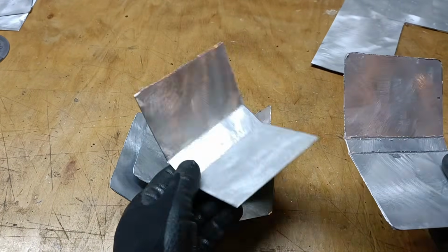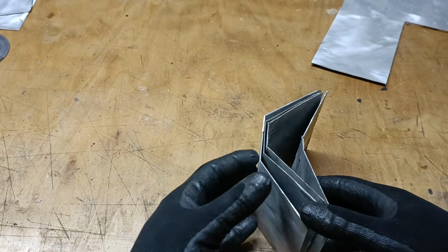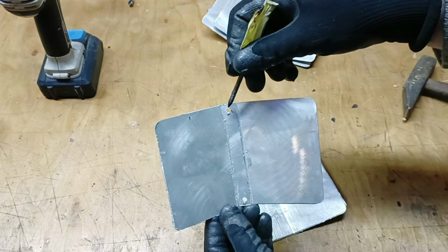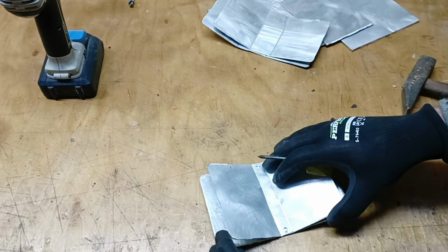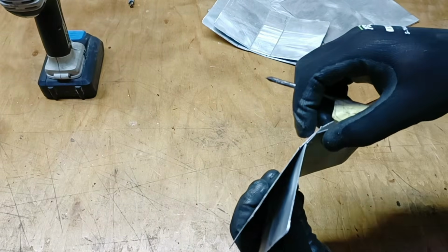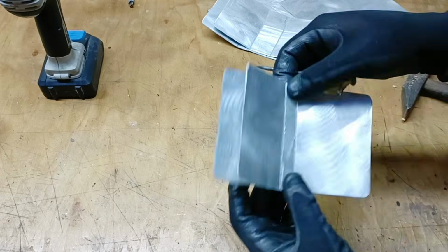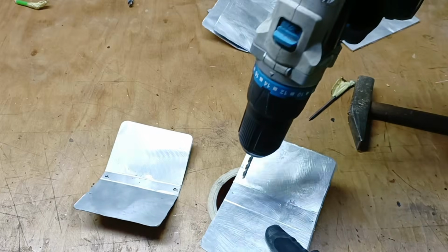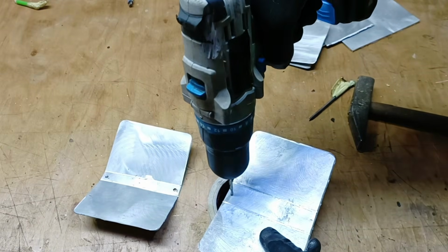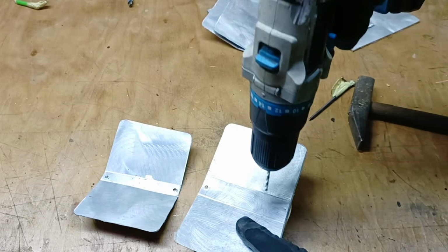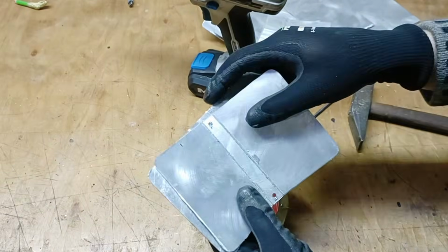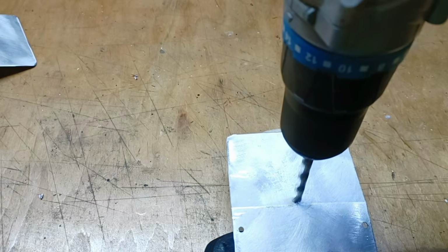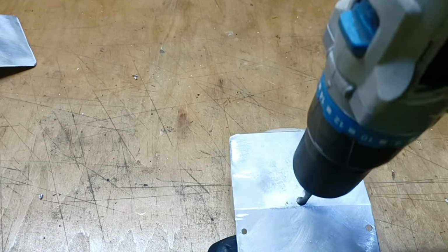The largest plate, which will be in direct contact with the Peltier cells, measured 17 by 10 cm and each subsequent plate is 1 cm shorter, resulting in the smallest plate measuring 14 by 10 cm. All 4 metal plates will be connected to each other using 2 rivets, as you can see in the video. Of course, don't forget to apply thermal paste to each plate first. As you can see, I'm making 2 additional holes of larger diameter. These are for threading the clamping tape, through which the heatsinks will be pressed against the Peltier cells.